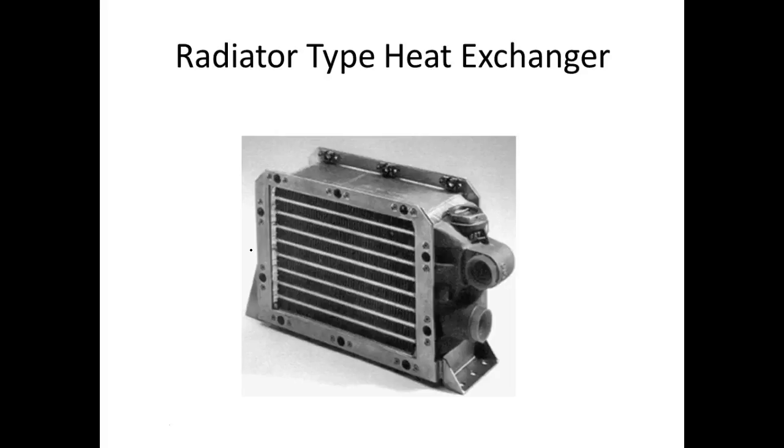Copper is better. It's also used in computers. We used to call it overclocking: you ran your computer faster than what it was designed to run. What you had to do was look at the difference between a copper heat sink and an aluminum heat sink. You'd see right off the bat that the size was a lot different. Copper heat sinks are a lot smaller. Sometimes in a laptop computer they still use copper because they're limited in space. They'll have a chunk of copper on top of the processor, and then run it over to where the fan is.